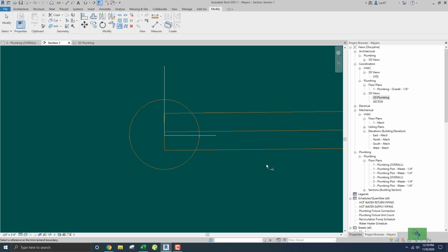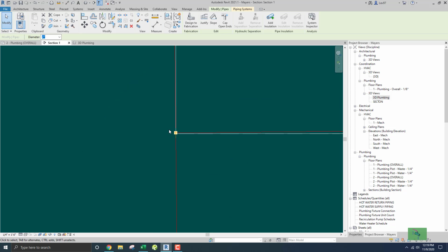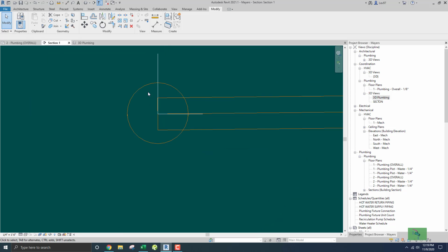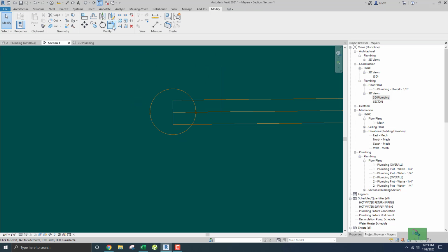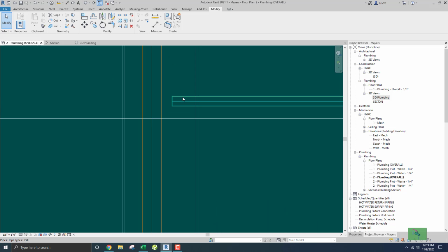Okay, and I think that with this, because it's not too much, Revit's going to allow me to scroll down a little bit more. That might be good. I'm going to keep it right there. Okay, and erase this detail line. Go over, move this guy over just a little bit, and trim it back again, right? Nothing different, nothing new, same time, same place. We're gonna go back to our floor plan and drag.